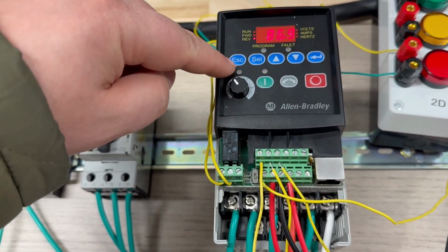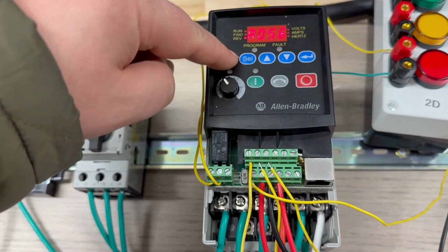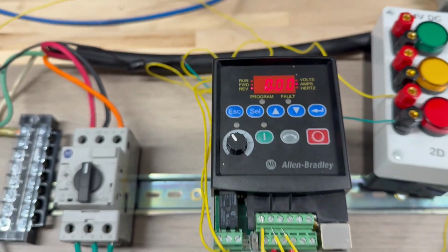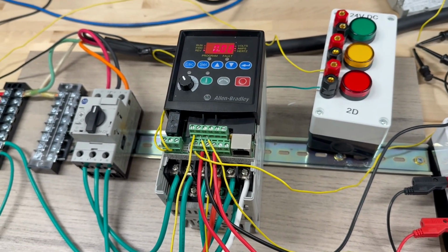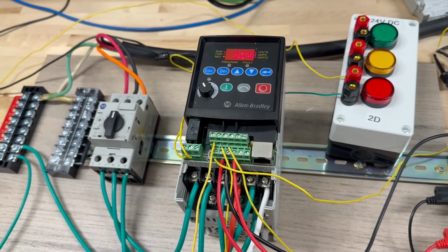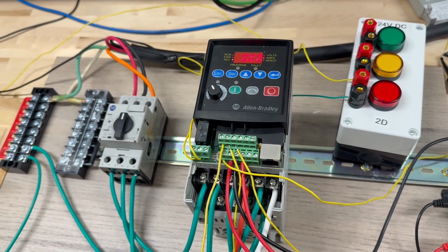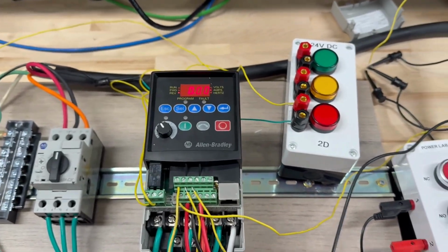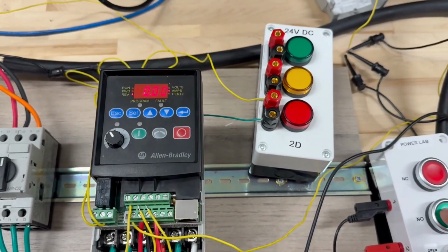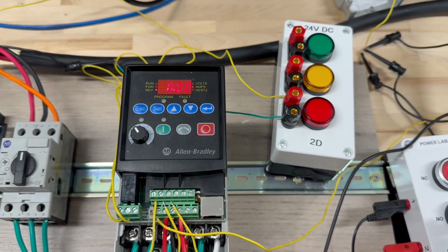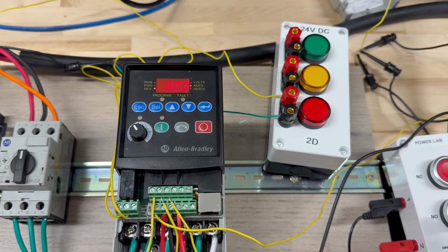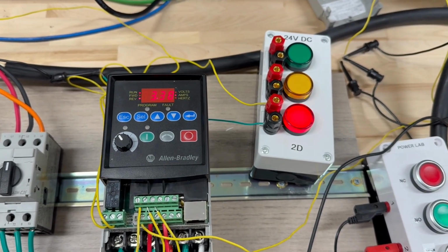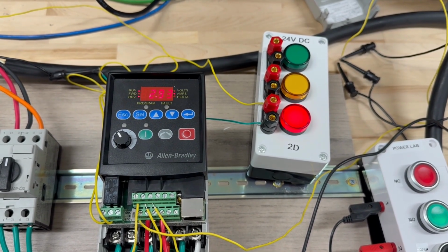So let's see that. I go to D3, which is able to monitor the amp. Now I can see the amp. I also gave enough time for acceleration, a big time so the motor slowly increases the frequency and we can easily see the current. So let's start. It should turn on whenever we are over 2. Probably whenever I turn this on, it draws too much current. So let's see. It is too much current. Now it's 3.3. This is the start, it takes a lot of current.